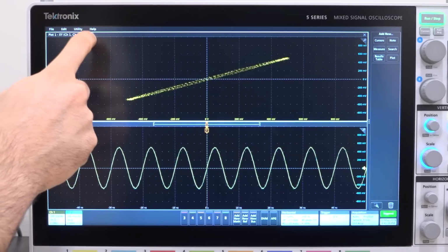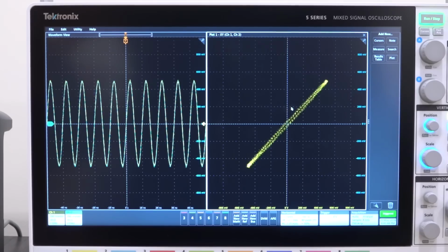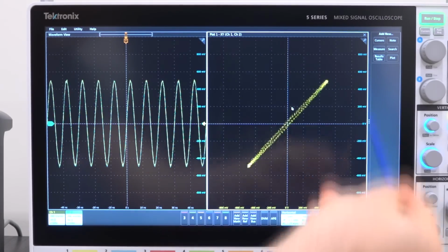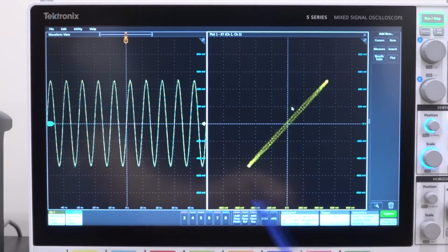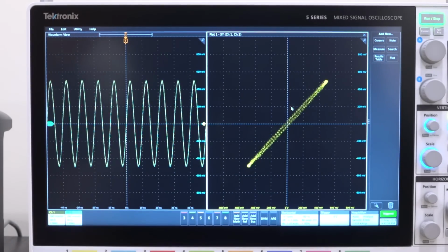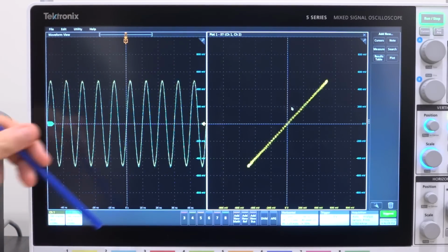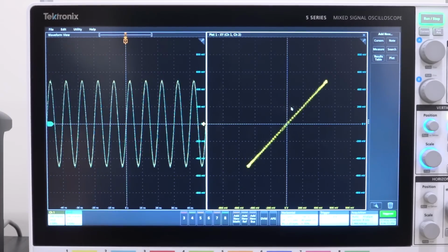Now I'm going to take this waveform from the top, and I'm going to put it here on the side so that we would be able to get a nice even spacing between the vertical and horizontal divisions over here. And you can see there's a tiny difference between them, and I suspect that's primarily from my cables. So I can go ahead and change that by about a degree. And now we're getting almost perfectly on top of each other. Now we're about 3 degrees off. And that means that if the scope is perfectly calibrated, then the reference phase coming at the two inputs into the scope are now perfectly in phase.